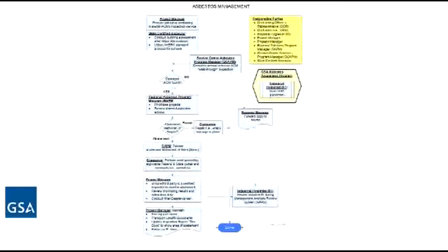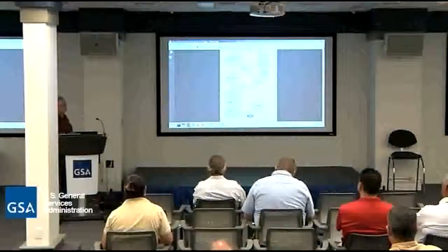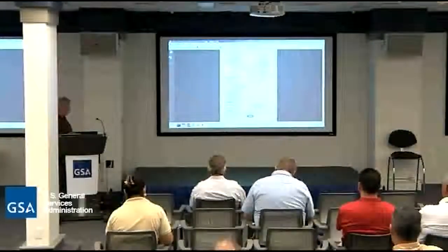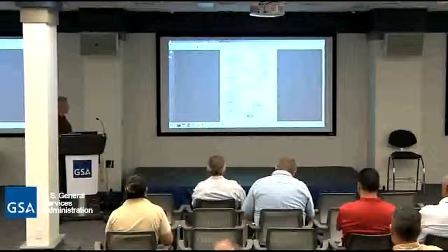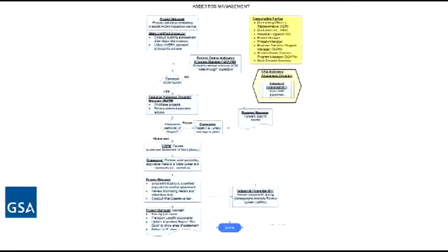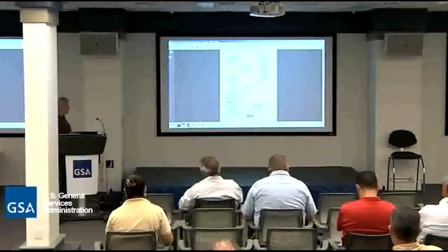There are some small patch jobs within the regulations that allow other individuals to remove small portions of it, but in general, an abatement contractor comes in and does a glove bag or a containment on it. If there's full containment on it, you follow all of CDPHE Reg 8 requirements, which also includes an end clearance. That's about it.